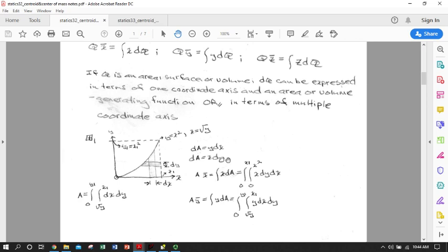Just a quick review. So this is one way to work a centroid evaluation of a continuous function. I didn't necessarily need to rely on the fact that it was invertible except to get the limits of integration, because I had to know what the function was with respect to either potential independent variable to know where to start integrating. So in this case, the function inversion ended up in the limits of integration. But otherwise, it's pretty straightforward. We add up little boxes to make a strip, and then we add up strips to make an entire area. And then of course if you needed to make up a volume, then you could just integrate over the limits in the other orthogonal direction.